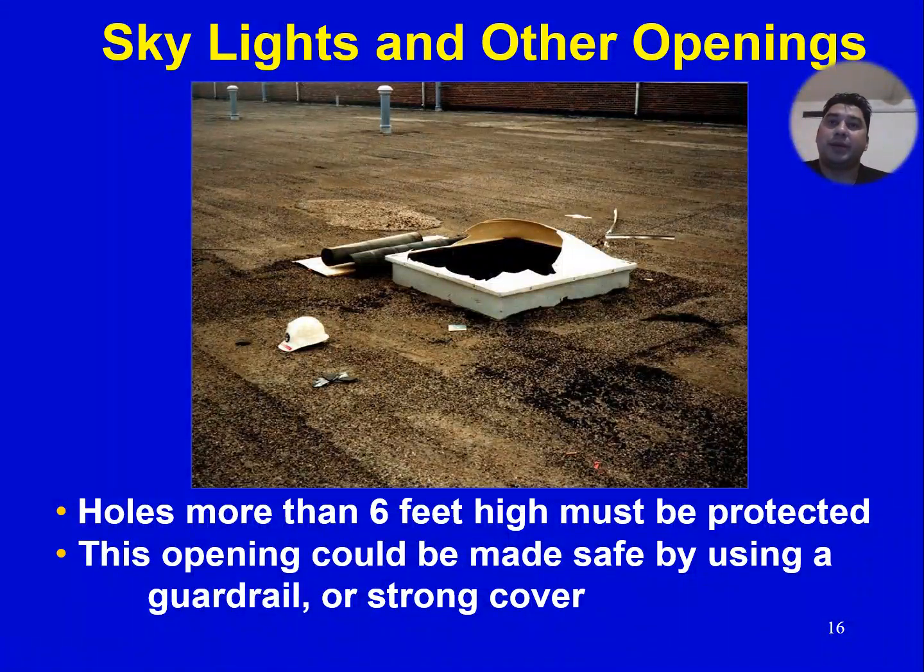Skylights and other openings. Holes more than 6 feet high must be protected. If there is any hole that is more than 6 feet in height, that should be protected as well. This opening could be made safe by using a guardrail or a strong cover.